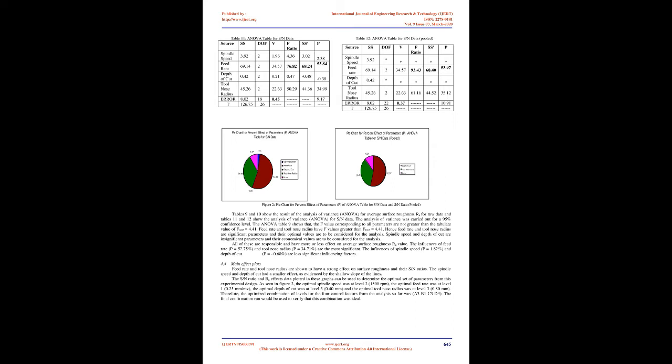4. Results and discussion. 4.1 Orthogonal array experiment. The number of process parameters is 4 and the number of levels is 3 and hence, L27 orthogonal array, 3-level orthogonal array, was selected for the analysis. 4.2 Analysis of raw data and S/N ratios. As response variable i.e. average surface roughness Ra is to be improved, hence smaller the better S/N ratio is used. Where η is the S/N ratio, y is the individual surface roughness measurements and n is the number of repetitions.